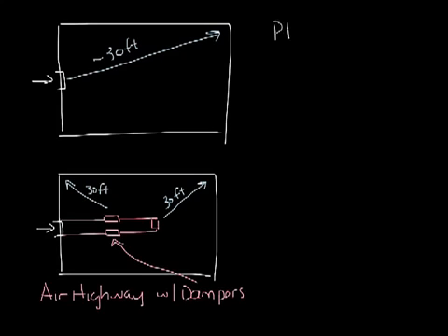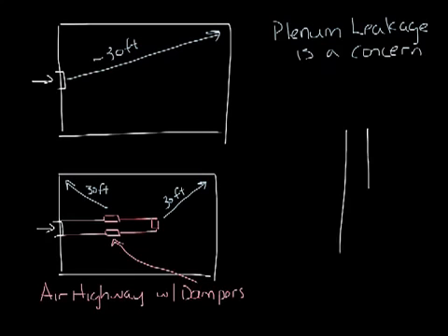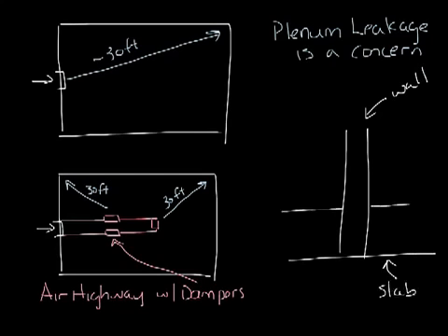Air leakage from the plenum is a very important consideration as well. On the room side of the raised floor, the carpet tiles will help seal the plenum, and any leakage will go into the occupied space, so it's not as big an issue. A bigger concern is sealing any wall penetrations in the plenum space so that supply air doesn't leak into the space between the walls, which is a waste of energy. Leakage is an issue that got a lot of press a couple years ago, but it can be handled pretty well with sealing the plenum during construction.